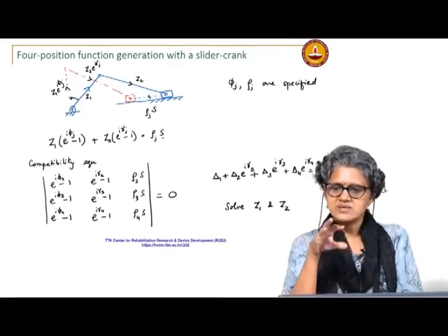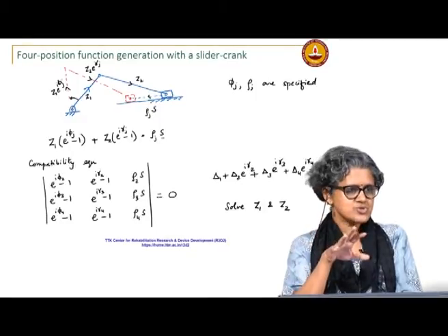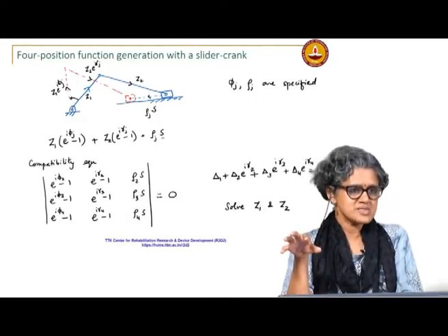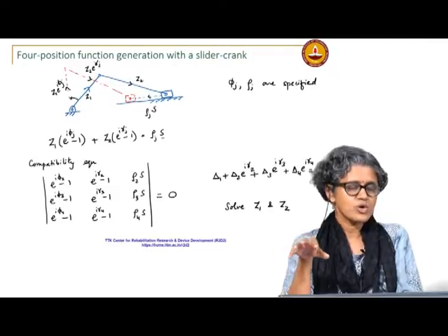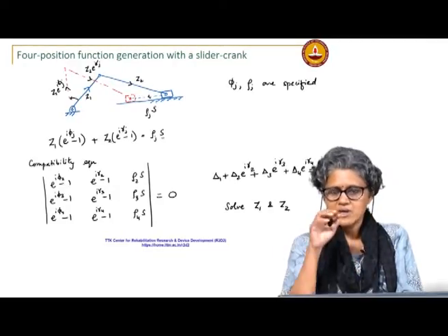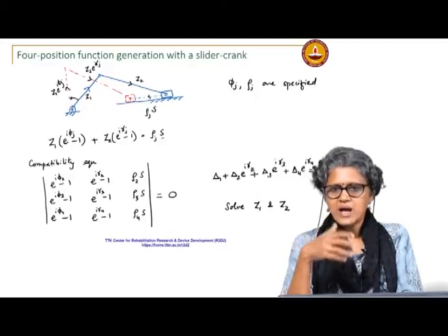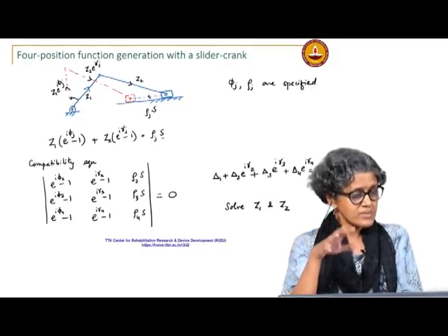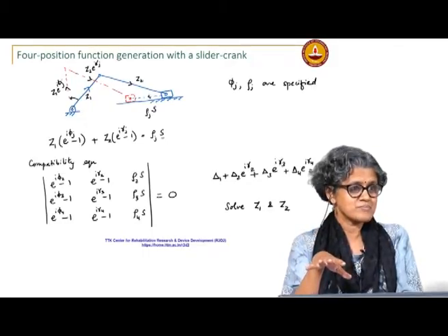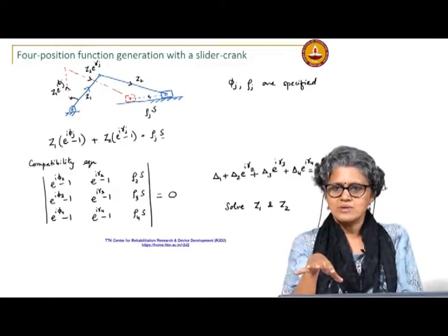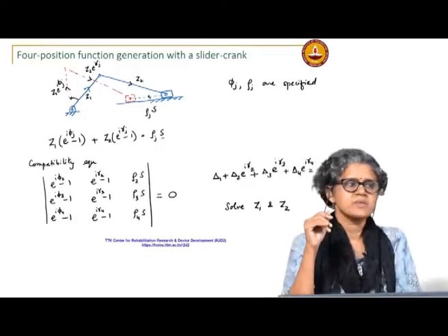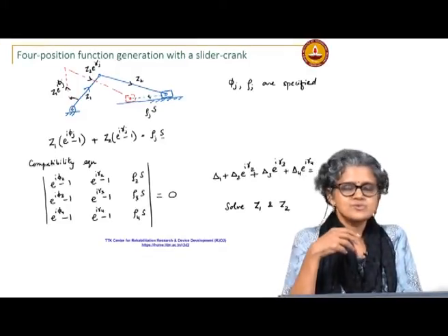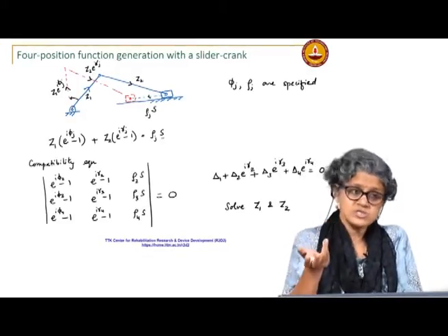For instance, for every mechanism that you choose, you can compute the minimum transmission angle, or if you want only a crank rocker, when you have an analytical routine, you can go through design choices more quickly. Setting it up takes a lot of time, but if you are going to go through a number of these, then it makes more sense to put in the initial effort to use an analytical method. Also, it is going to be more accurate.